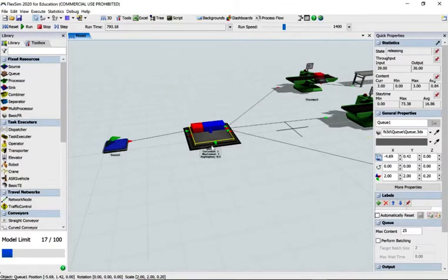If that's a little bit small, you can look down the right hand side for quick properties of whatever you selected, so you can see the throughput, how many objects have gone through that queue, is up to 51. You can see how long objects stayed there. So some are going straight through, which you would expect for the first one. It's just basically going to the queue and bouncing straight off. But the average is 18, and the maximum wait can be up to 89.